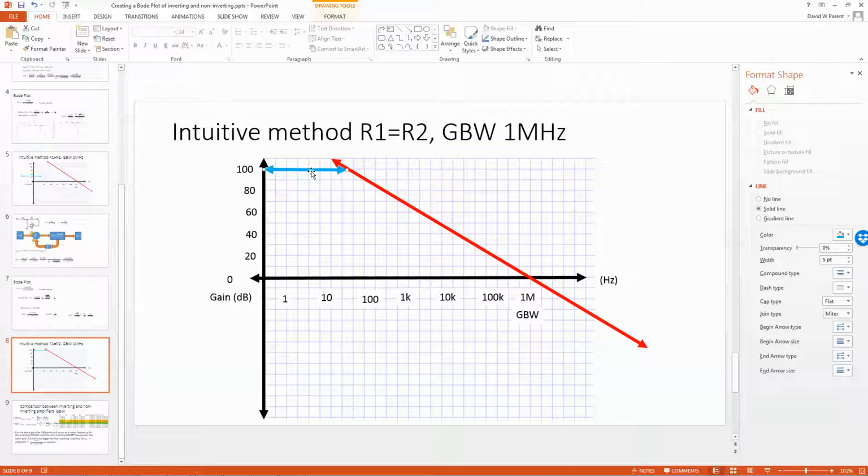And so what we would get here, and this is the hard part, is you should get minus 180 degrees of phase because the gain is minus 1, right? Or I'm saying the gain is minus, this one down here. So the gain is minus 1, which gives us 0 dB. Almost out to here, and I'll tell you why it's not exactly out to there. So the phase would be from here to here, minus 180.